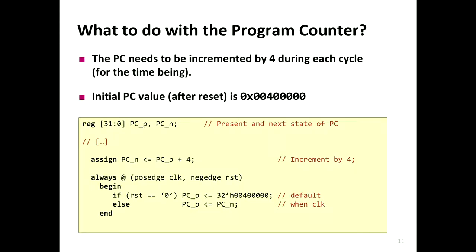What's an asynchronous? Yeah, sure. Is there a particular reason why we use the falling edge of the reset? Good question. It's historical, more or less, because of some of the technologies that we used in the past. But an easier answer would be that it's much easier to get glitches in the circuitry, which are quick shots of voltages, which means your system is going to get reset unnecessarily. So it's much more stable when you look for a high-to-negative transition, because this kind of glitch is very rare.